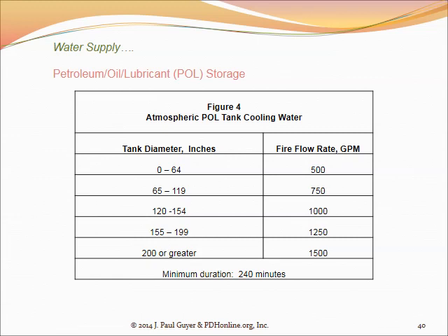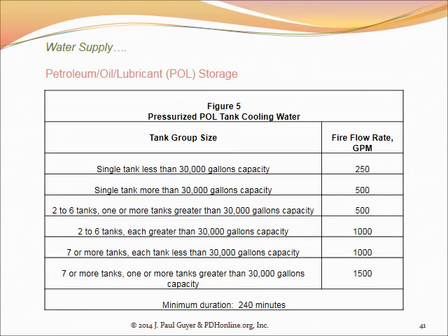You might be thinking, well, why is only the tank diameter of consideration here? Why not the tank height or depth? Well, the reason is that with a fluid storage fire risk, what burns is just the top surface area of the fluid, and it doesn't matter how deep it is. The only part that's burning is that part at the top. So that's why depth of the tank is not taken into consideration. And another illustration here in this figure 5 of how DoD handles multiple tank installations.